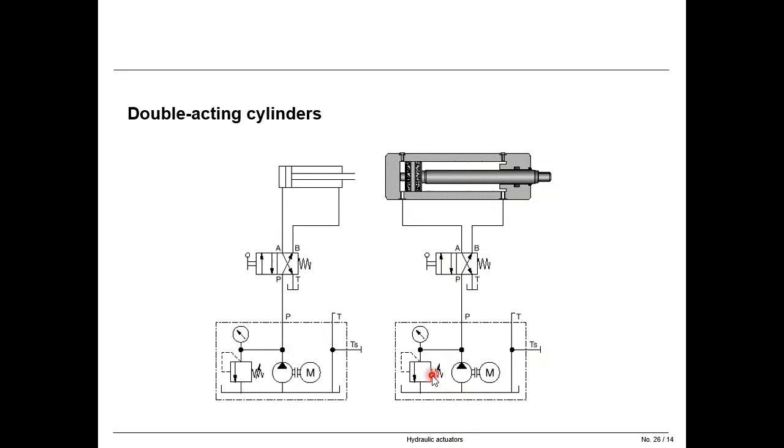So you know the pressure is important in a hydraulic system, but it is also dangerous. So we have to keep the pressure at a certain level, which can be safely carried by the system. Therefore, we have here the pressure relief valve, and you see this arrow here.